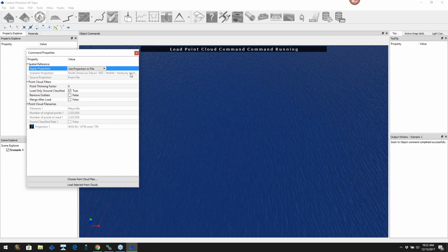Right. So now in this case, maybe I do want to apply a thinning factor. I got 3 million points here. I'm just going to reduce it by 3. Okay, so basically, if I thin something by 3, that means the points that are being loaded would be like 1, 3, 6, 9. You know, that's the point number that's being loaded.